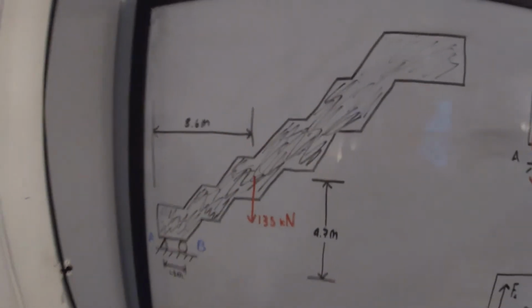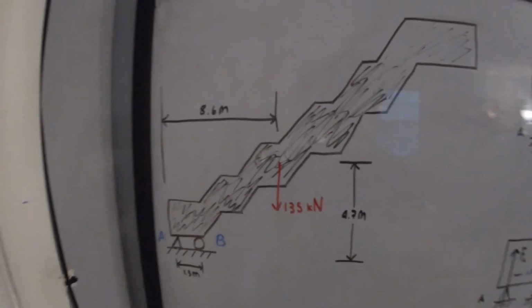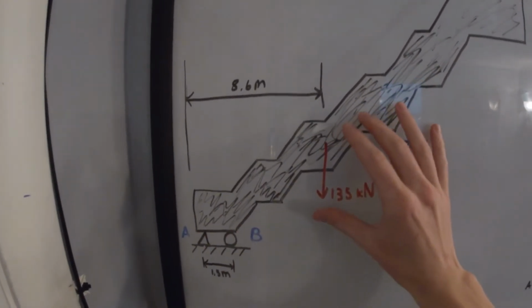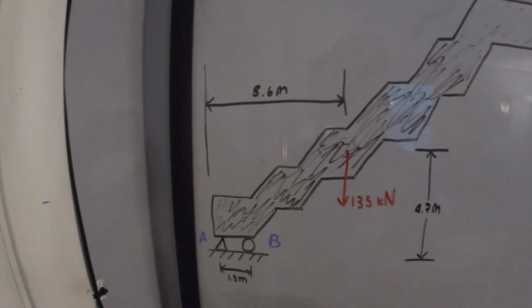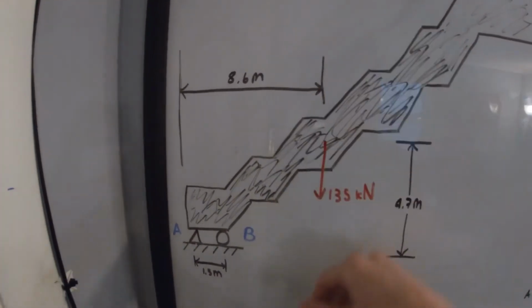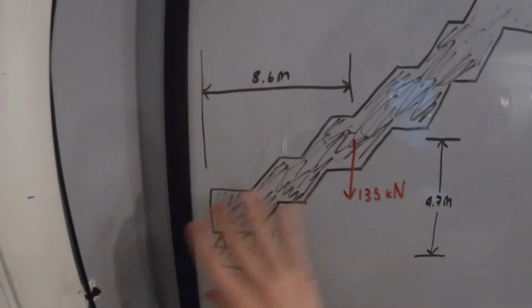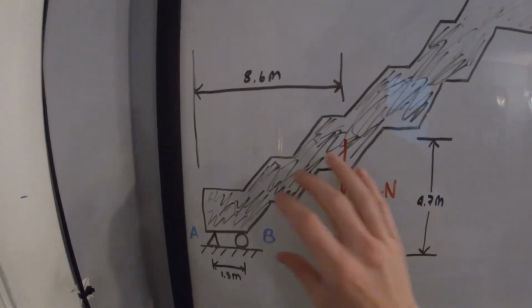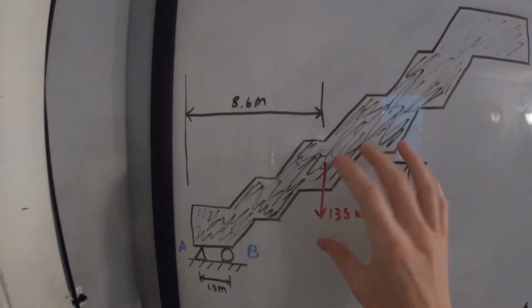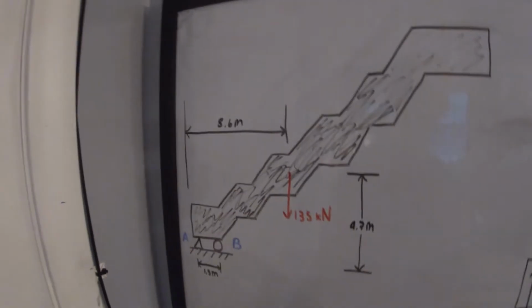That's kind of confusing to say in words, but it's kind of intuitive because it's just saying that if we were to move this force to A, we can just take this force and move it down to A, but then we also have to apply at A the moment that this force in its original location causes about A. So we're taking this force alone, moving it, and then replacing it with a force and a moment. And that moment, again, is the moment that this force causes about A. I know I just said that like three times, but that's the most important part of the problem.